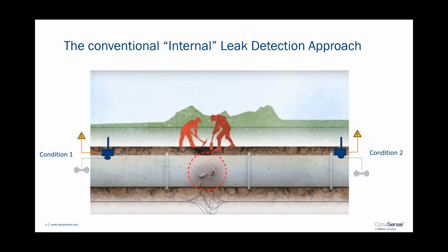So in general, they're very well adopted, very well accepted as providing a good approach to leak detection on pipelines. But they can be quite slow when working at their highest precision, looking for the very smallest leaks that require time to statistically average out the evidence, and their positional resolution will not be very good because, of course, they can't be everywhere.